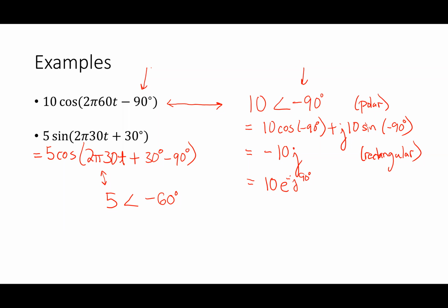The important thing is there is this sort of up and down voltage happening right there. Once I know what the frequency is, I don't really care about the details of that waveform. What I care about is this phasor idea. If I just keep track of the angle and the amplitude as I work through the circuit, then I can really make the math a lot easier.